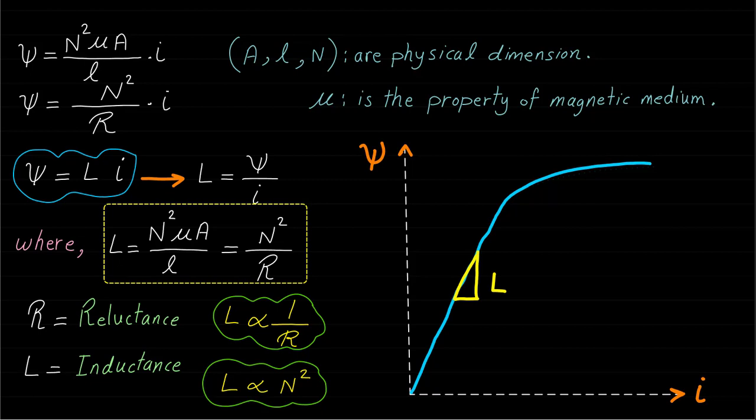Basically, if the magnetic circuit is saturated, the slope becomes small, or in other words, we lose the inductance. Usually, the inductance is assumed to be linear or constant to simplify the calculation of the magnetic circuit. However, saturation of the inductance is considered one of the uncertainties and must be considered and compensated in some applications.